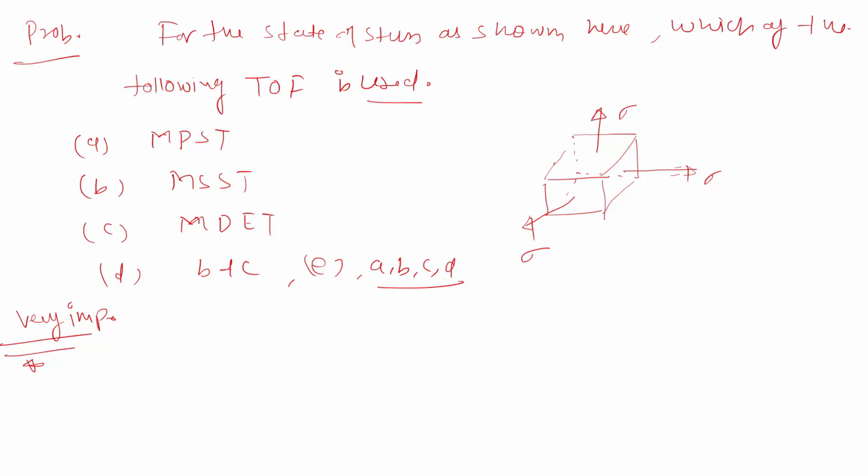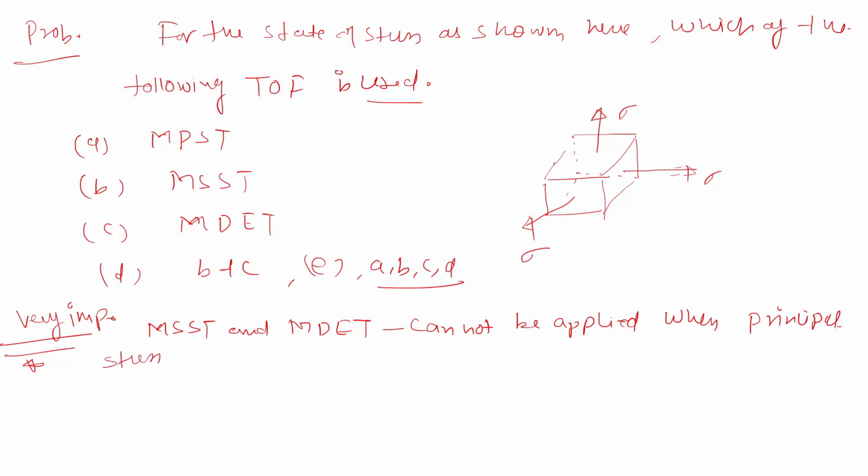So here we have to say that MSST and MDET, maximum shear stress theory and maximum distortion energy theory, cannot be applied when principal stresses are equal in magnitude and of the same nature.